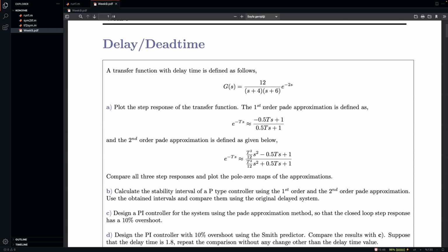Because, first of all, we have a stable transfer function here. This is the first order approximation, which you get here. And in the Taylor series, you might end up with unstable approximations, which you wouldn't like to have. So that might cause some issues. But here we can see this is a special approximation method, and we will see how it is working and why it is working actually in a minute.